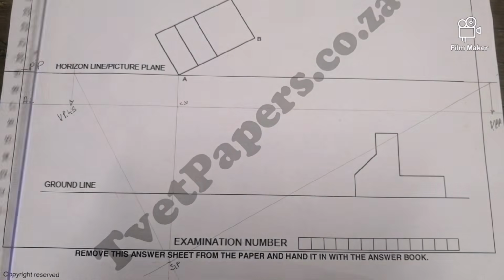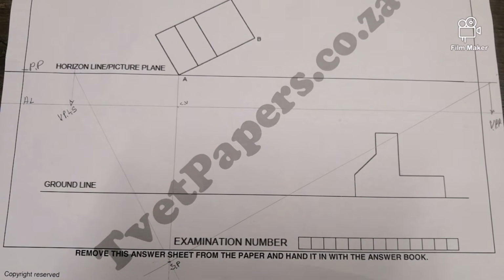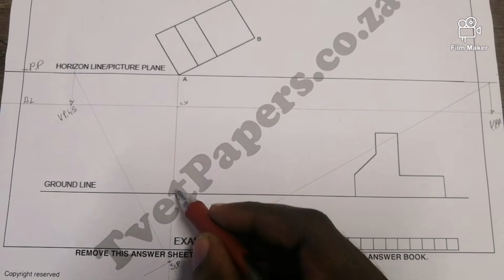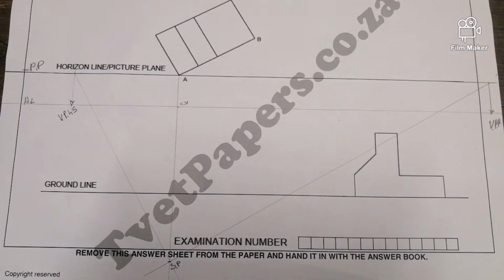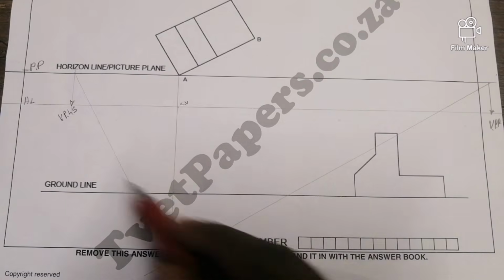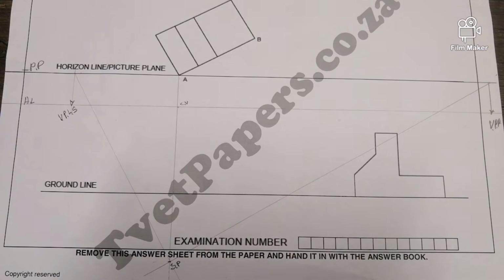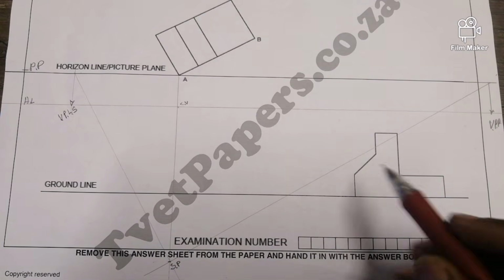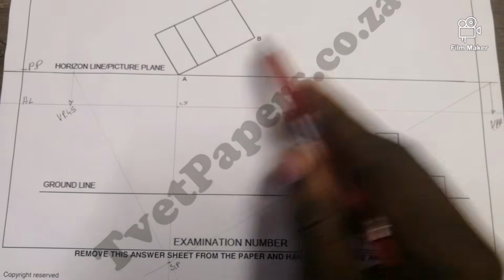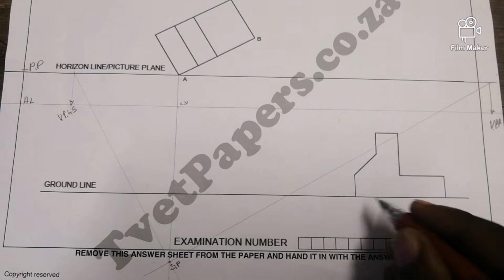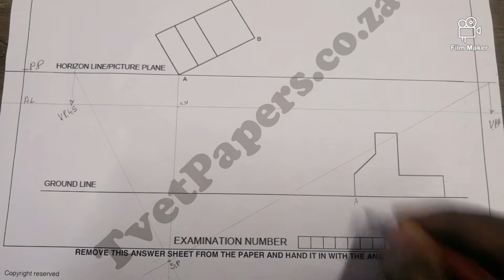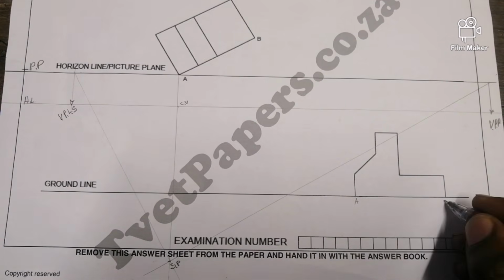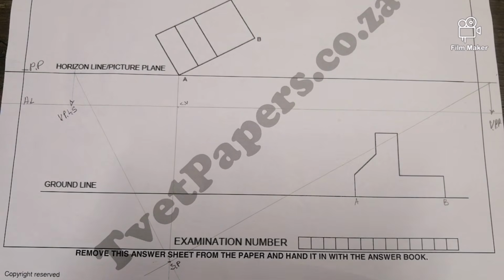Right, then from there I am going to take this point to the vanishing points, both left and right, and this is the ground line, isn't it? So if we were to label this AB on our right view, this A is going to be here, understand it? This B is going to be here, understand?